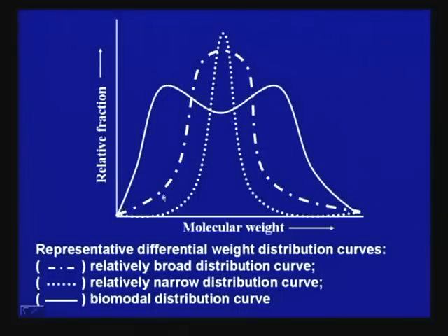So, that flow behavior, flow characteristics, all these things depend on the molecular weight distribution. Now, if there are small molecular fragments present in a sample of polymer along with high molecular weight molecules, high molecular weight molecules contribute to the strength properties, and low molecular weight fractions contribute to the processing characteristics. So, the amounts present on the lower side of molecular weight contribute to the processing characteristics of the polymer, whereas the higher molecular weight fraction contributes to the mechanical properties, thermal properties, all those properties.